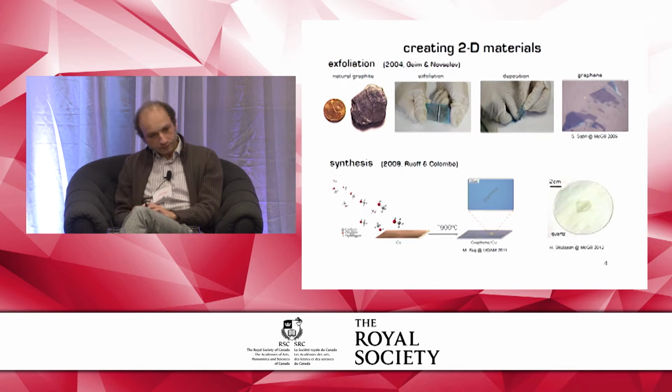So, as was already mentioned, the technology for manufacturing graphene is interesting in and of itself. And it was in 2004 that Geim and Novoselov and their team came up with the technique of exfoliation. And the general idea is as follows, that you take a lump of graphite, and it should be a very high quality piece of graphite that is free of other impurities if you can find such a source. And you take some tape and you essentially peel away the surface of the graphite material.